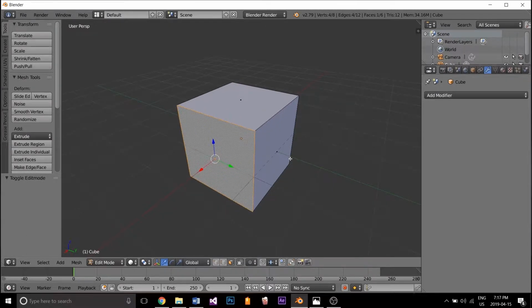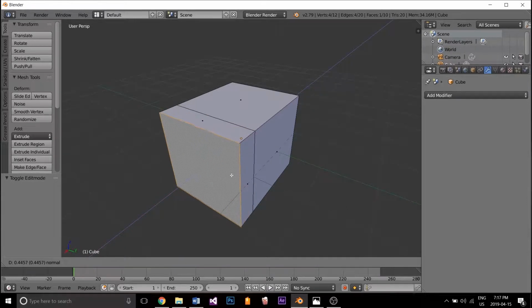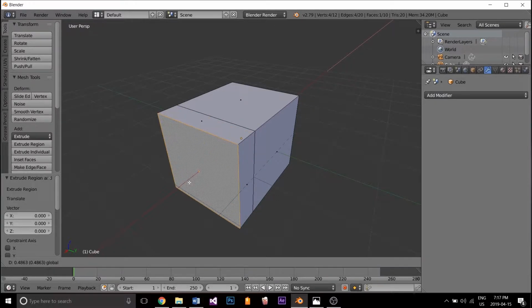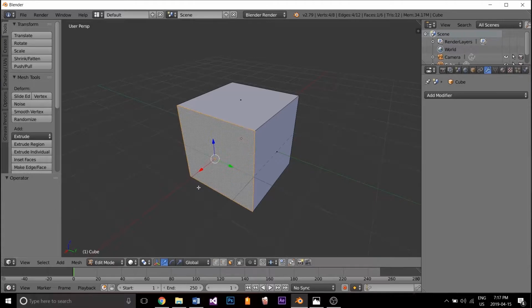Okay, so from here our different hotkeys are E to extrude, and here we, if we extrude on whichever face, it follows the axes that is most likely the way that you're moving. In this case, it's following the x-axis with the Z color. Right click to cancel the motion, and then we can see that it's going on the x-axis. And then Control Z to undo our work.